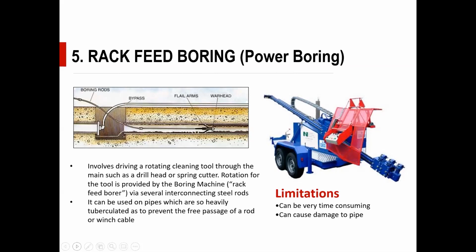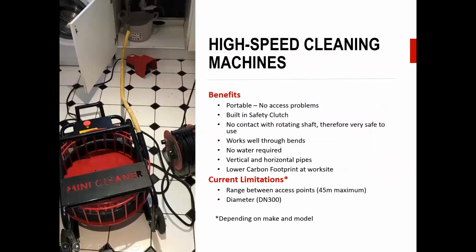So it's like a mechanical version of rodding a pipe. It can be time consuming. I've been on job sites where, to do some pipe rehabilitation on the water main, I've been on sites 2 or 3 days while they clean the water main, and then the lining system is very quick, but the cleaning side can be very time consuming, certainly for rack boring and drag scraping and pigging. So they're the traditional methods.